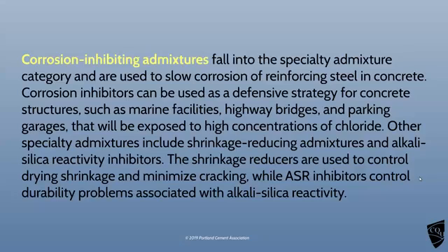The corrosion occurs when the concrete is naturally alkali, but over the course of its life, carbon in the atmosphere reacts with the cement part of the concrete, and it's called carbonation. It's normally at the rate of about 1 millimetre depth every year, and when it becomes carbonated and the alkalinity is gone, it no longer protects the reinforcement.